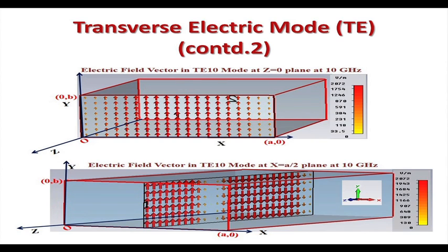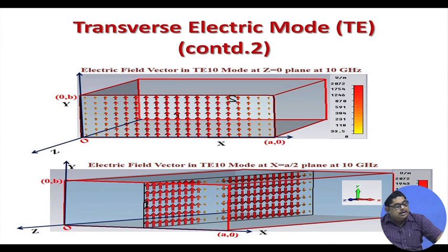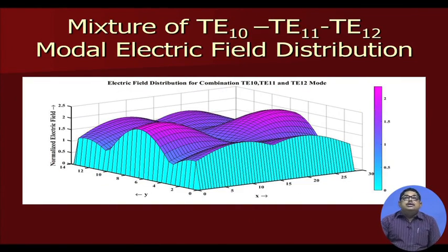This type of various modes, but all of them have, you see, in the transverse plane the electric field lying. We are seeing a longitudinal plane, it is basically the waveguide. Between that, we will see that the field distribution is like this. There is no component in the z direction. So, the electric field is entirely in the transverse direction. And as I was saying, by mixing these various modes, you see, if the electric field distributions are mixed, then you get a field distribution like this. So, all these various things are linear combinations of these modes.